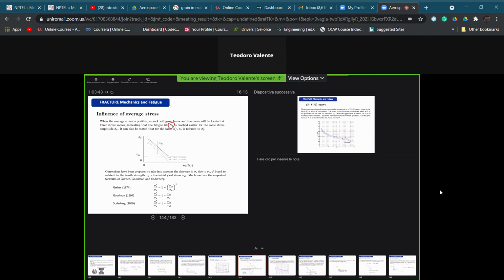And thus, there are some models which are going to work quite well, which allow us to define what is going to happen if we move from the standard fatigue cycle, in which also at lab testing we take an average stress equal to 0, to a real fatigue testing or fatigue condition where the average stress is not taken equal to 0, but it's positive.